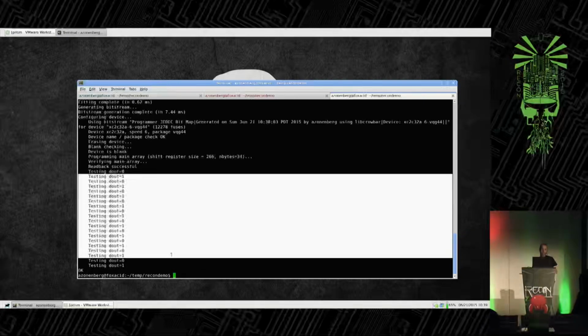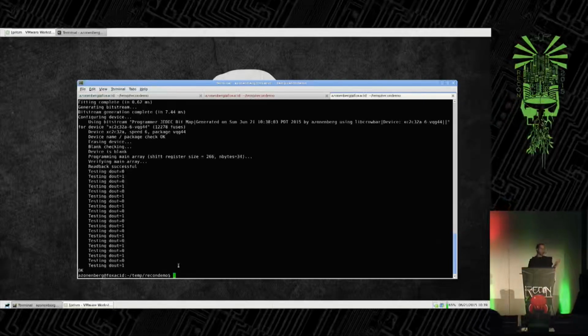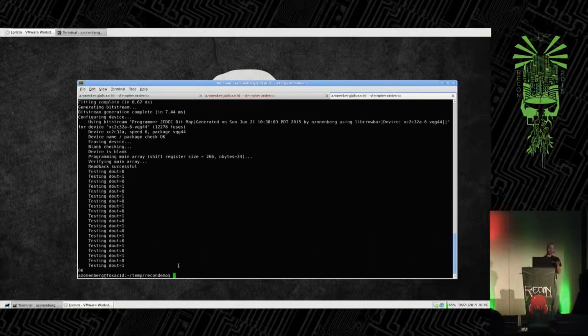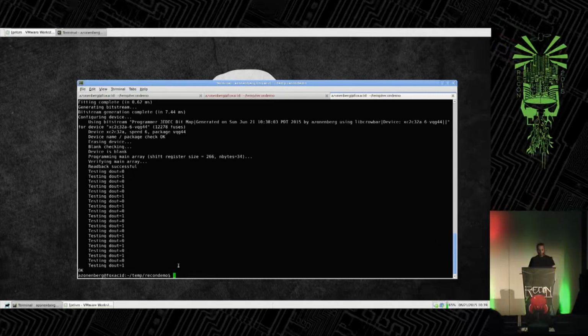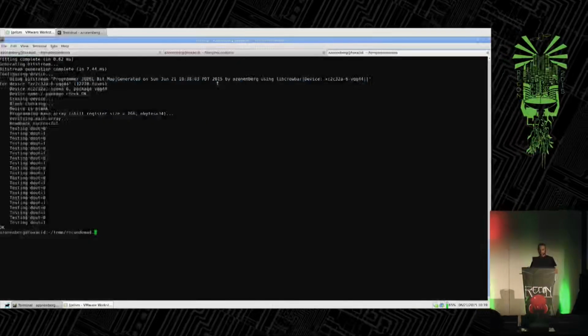And then we just bit bang the output as 0 and 1, and it confirms that the loopback going back to the FTDI chip does have the values we expect. One of them is X, one of them is X prime. So that looks good. Now let's see what happens if we actually want to reverse this.